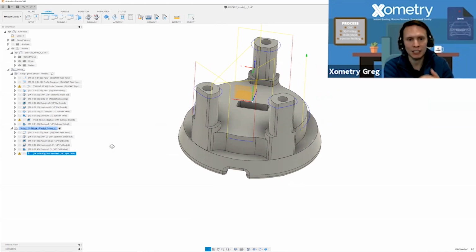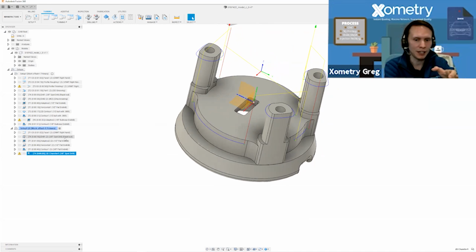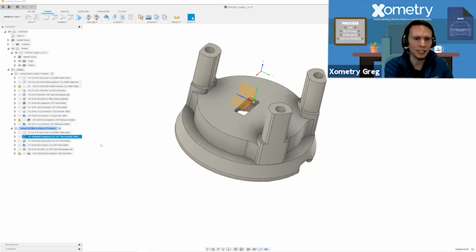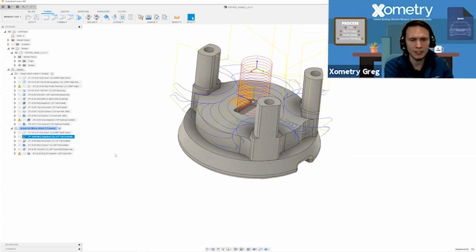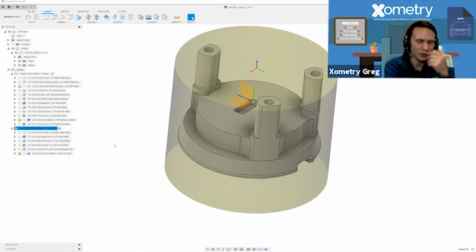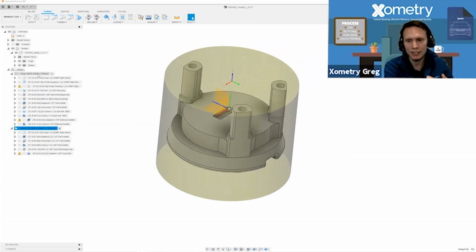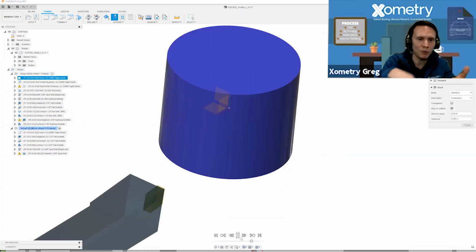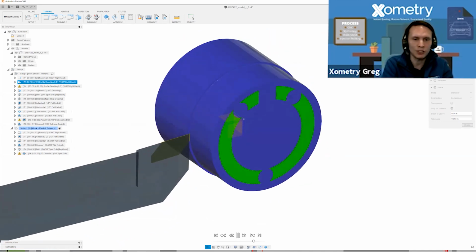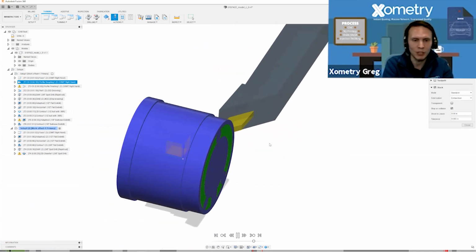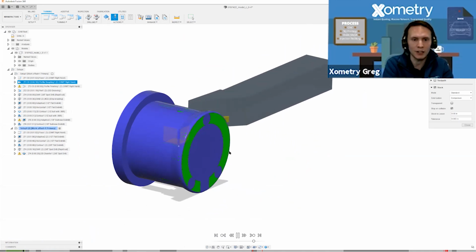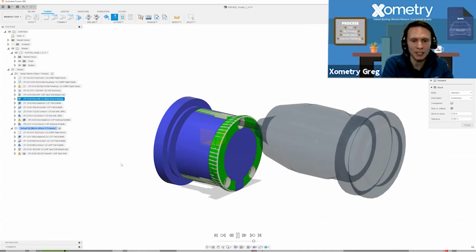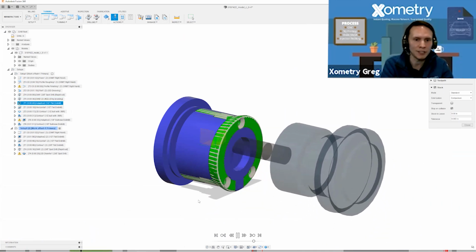And I've personally had experience where we saw a very specific scientific application that we were making a part for, and they said definitely do not machine deburr this internal edge. And it just kind of racked our brains. We asked them why, and it's not that the machine deburr is bad, they just didn't want someone to do it manually because it got such a rough edge on it. So once we showed them what a 20 thou deburr looks like with a machine, they're like, oh, that's awesome. It's more consistent than the product that we received before. Yes, please do that. We were able to change some minds there because of how consistent that experience is.